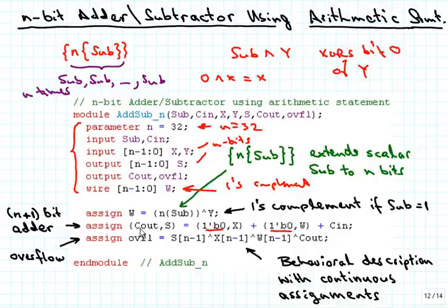And then in the end, we have to compute overflow, and the way we do this is we recreate the carry bit C sub n minus 1 by this computation here. So this is equal to C of n minus 1. And then we XOR that with carry out, which is Cn, and in this way we get the overflow condition taken care of.